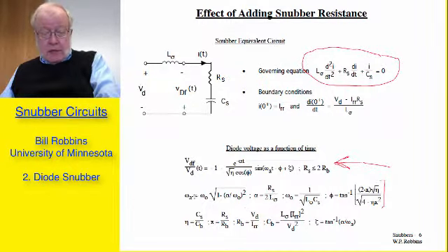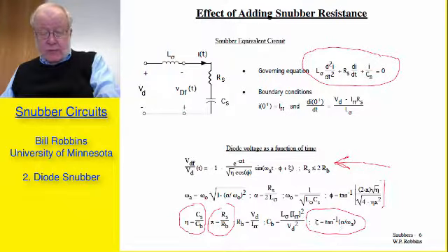Eta is the normalized capacitance. That's this parameter right here. X is the normalized resistance, Rs over R base. R base is V sub D over IRR. C base is the same quantity that we defined earlier. It's equal to L sigma times IRR squared divided by V sub D squared. And then finally the parameter xi is the inverse tangent of alpha over omega A.